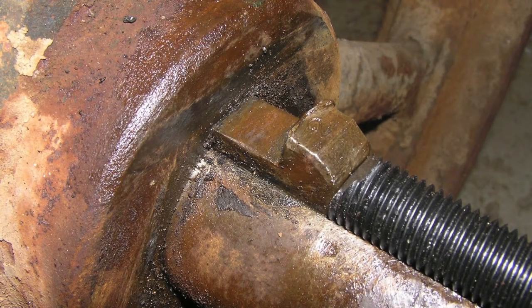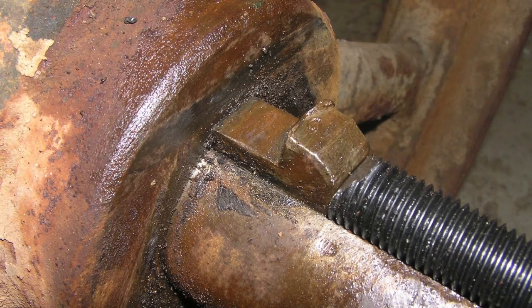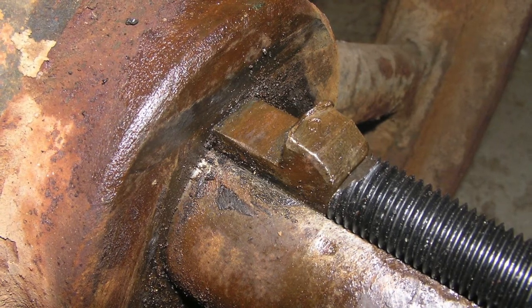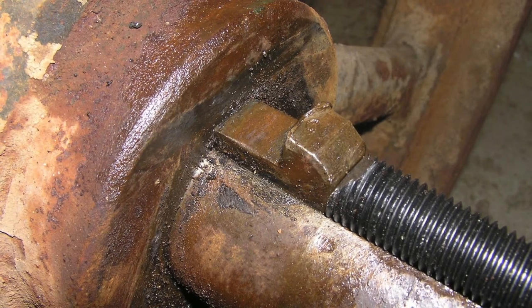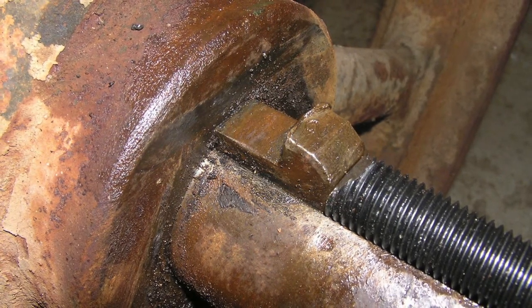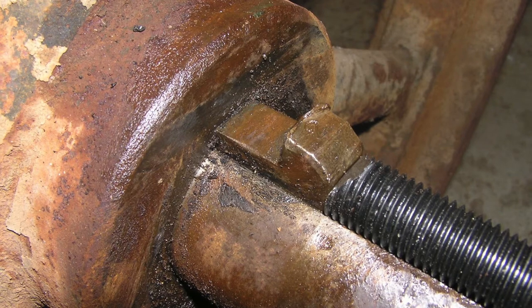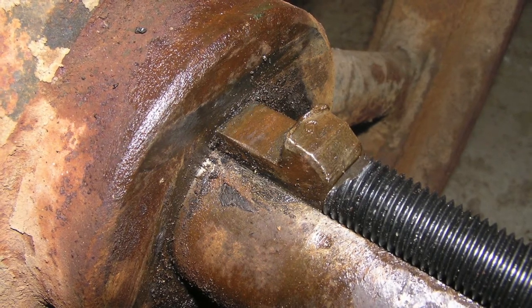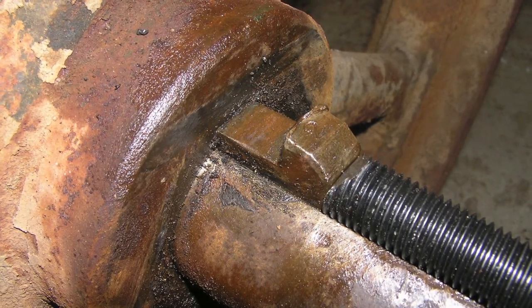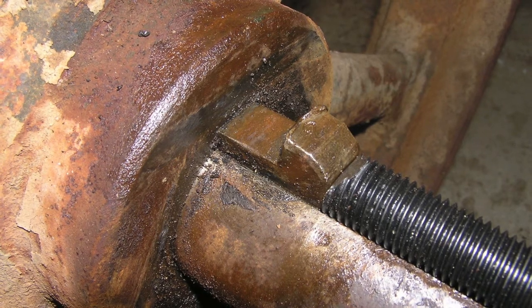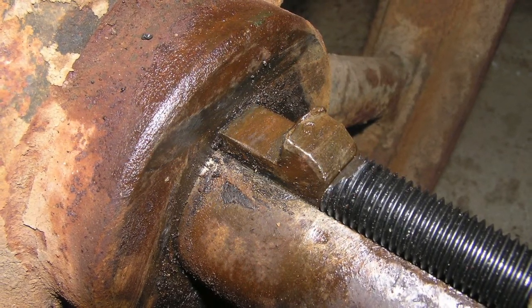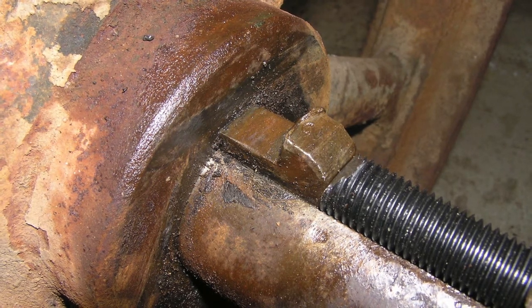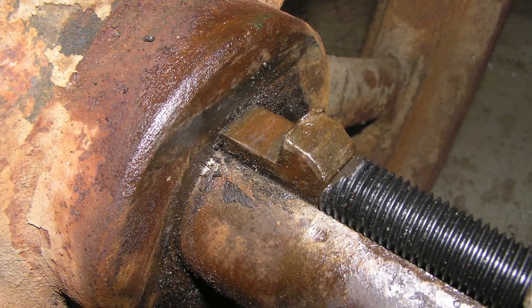Failure methods of flywheels are few and far between, since they are really only just a mass rotating. Failure methods of flywheels mainly come from how they are attached to a shaft. As seen in this picture, the flywheel is attached to the shaft through the use of a key. If this key were to break, the flywheel would not stay on the shaft, and rotation would be hindered.